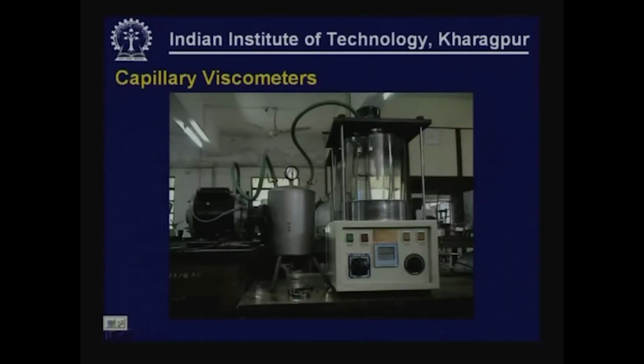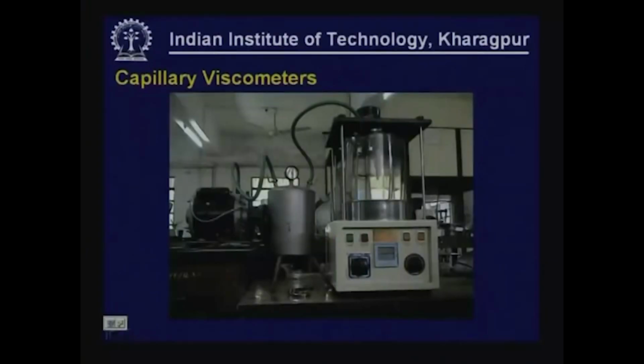In some cases, depending on the viscosity of the fluid to be measured, which again is a function of the test temperature at which you are conducting the test, a vacuum arrangement will have to be applied for certain test procedures. If it is a smaller temperature, the viscosity of the fluid will be more. So, there are various arrangements that are possible, with vacuum and without vacuum. Different types of capillary tubes are available, and for each arrangement there is a separate calibration factor. Once you get those timings from this testing arrangement for a given temperature, we can get the corresponding kinematic viscosity.